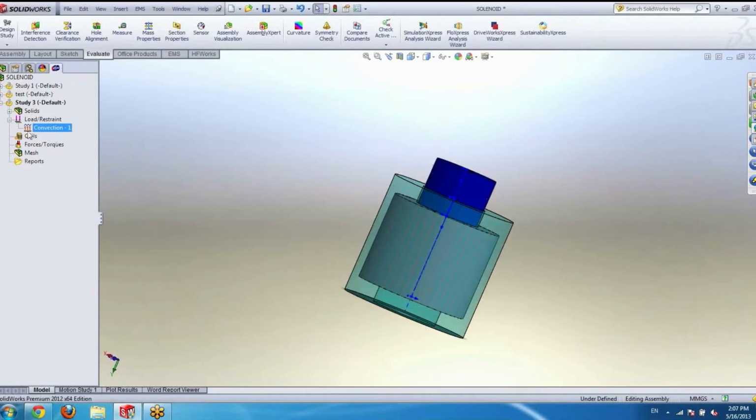Okay, right, and then also the coils. So basically you have two options here. You can set up a wound coil or a solid coil. In the case of solenoids, it's mostly going to be wound coils. And this is an advantage we have.